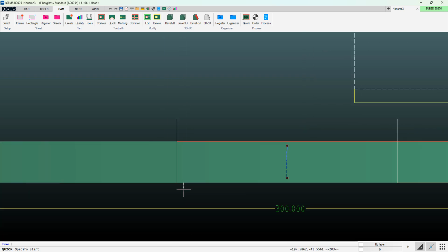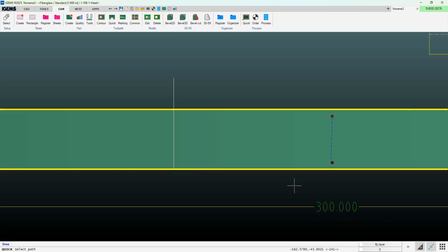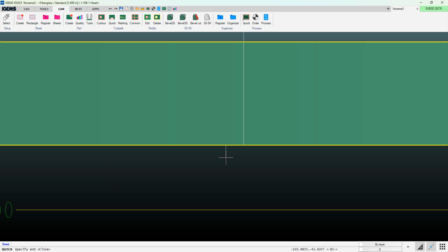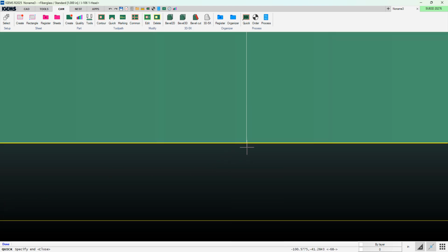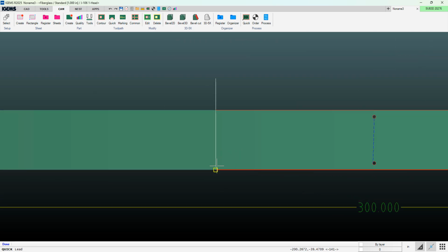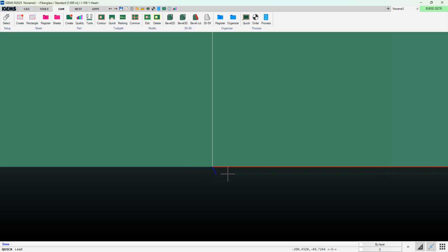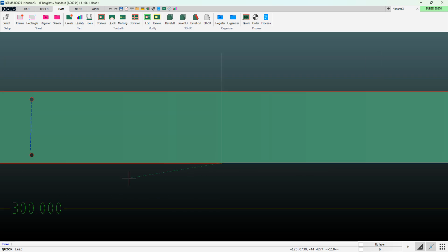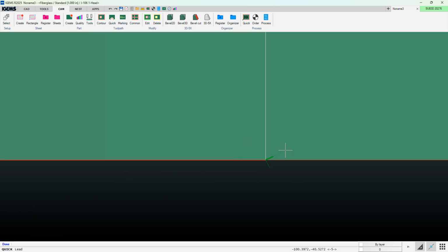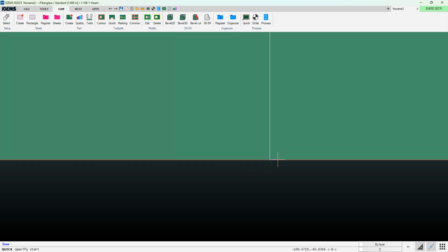And then we'll do the bottom in a similar fashion. We'll go endpoint and left click when that's highlighted. End, we're going to right click endpoint there. Left click when that's highlighted. And then my lead in, again, this one I want to be on the right side of the line there. So it's like that. I can hit enter. And lead out, again, if I want to overlap a little bit, once like this, I can hit enter. And enter and close.